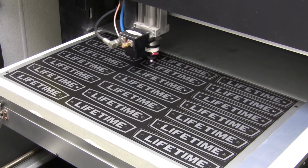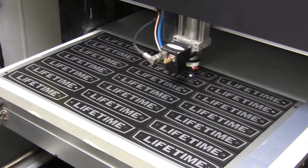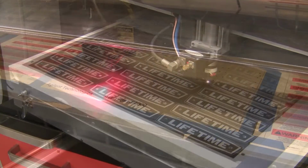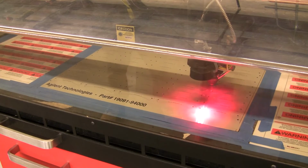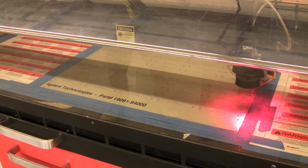Laser cutting uses optics to direct the output of a high-power laser at the material, which then either melts, burns, vaporizes away, or is blown away by a jet of gas. Because lasers do not use any type of tooling, there is no direct contact between the laser device and the material, reducing the chance of contamination or accidental marking. And because lasers create a smaller heat-affected zone, the risk of material warping and deformation at the cutting site is also reduced.